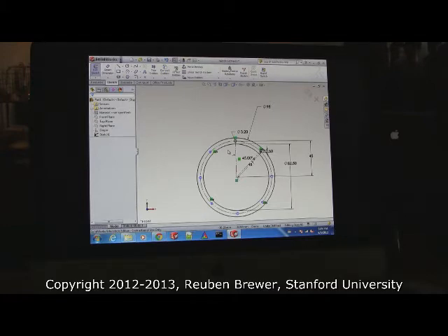Okay. When you did the circular copy, you did something interesting. You took 2 holes and copied them 4 times, rather than 1 hole going around 8 times, which you could also have done. The reason I did that is because we have 2 different diameter holes. If you look at your screen, one's 3.2 and the other's 2.6. Ken's right, we could get the same geometry by just copying 1 hole 8 times, but then they'd be different diameters. Actually, let's just test.